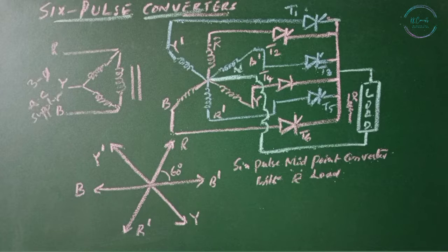6 pulse converters. Because of the requirement of a special type of conversion transformer, 3 pulse converters are not popular. The conversion transformer is used to prevent demagnetization for large outputs and least ripple content. A 3-phase controlled rectifier with higher pulse number is used. Generally, for industrial application, 6 pulse and 12 pulse converters have been used.